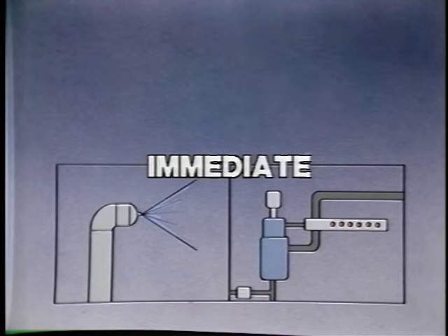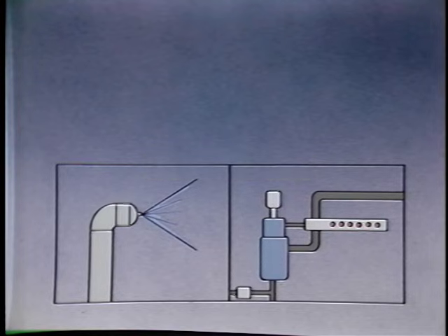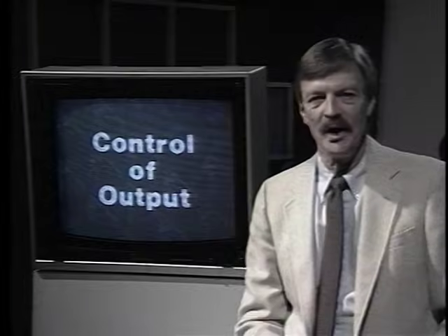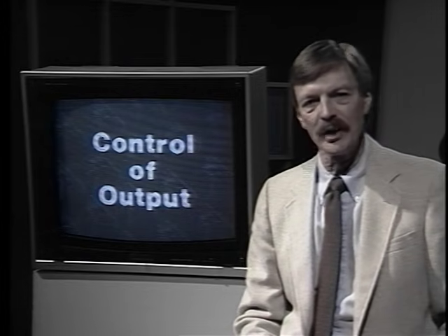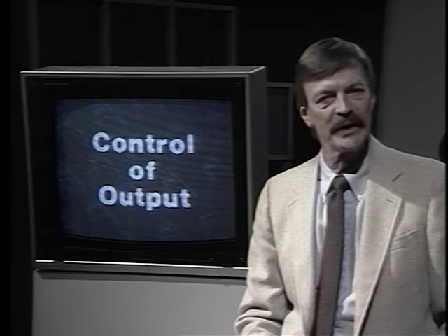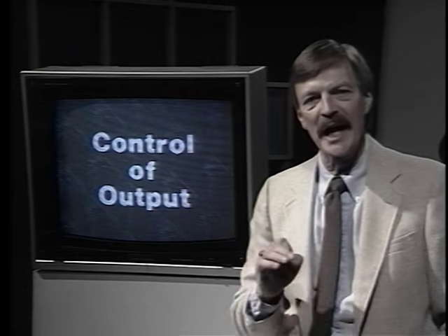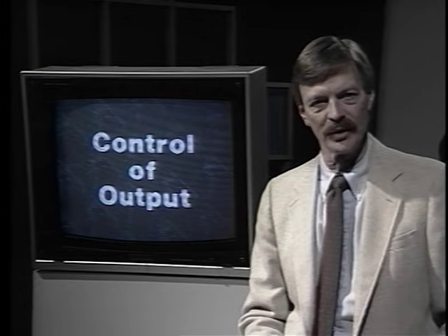The steam and water spray methods have immediate response. The output of the steam units is already vaporized, and the water spray medium is atomized, which immediately mixes with the air. Once the humidifier has been turned on, it must track the required changes. Its ability to do so is dependent on how its output is controlled.